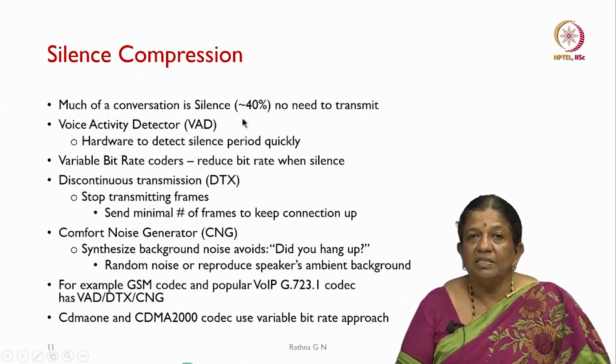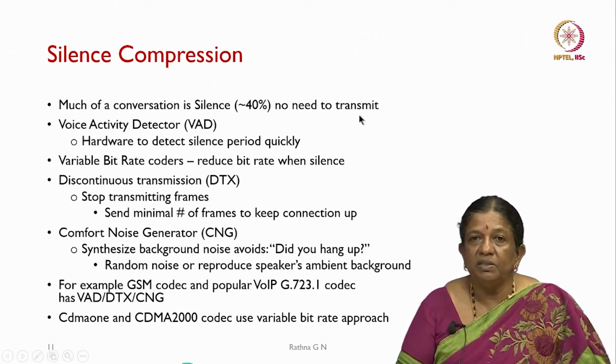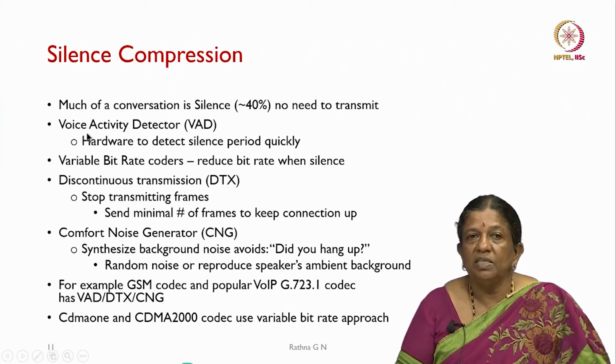According to the standard, approximately 40% is the silence zone. So we need not transmit that, but it has to be incorporated at the receiving end. It uses a voice activity detector, VAD, which is hardware to detect silence periods quickly. So you are building this in the hardware.